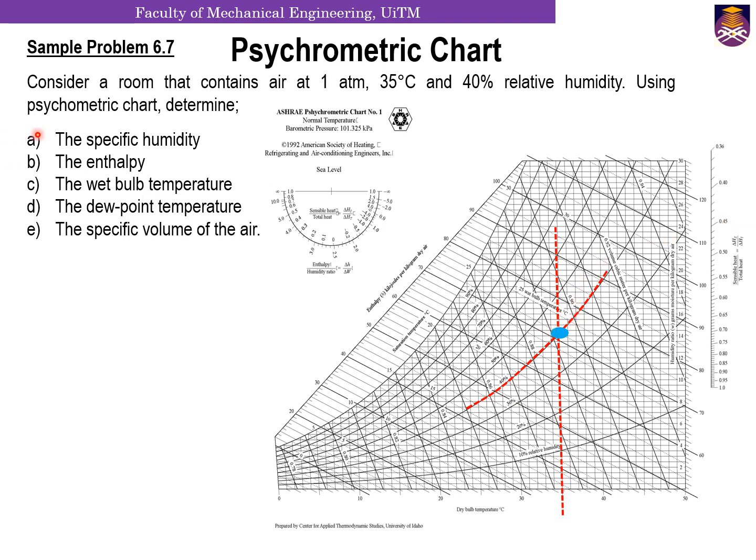Now based on this, we want to find what is our specific humidity. So to do that, from this intersection point, you pull a line straight horizontally so that you cut this axis, y-axis, to find the value of your specific humidity. So wherever you find the intersection here, so based on the scale given here, you find out what is the value. That will be the value of your specific humidity. Next, to find the enthalpy, we draw a line again parallel to these lines until we intersect this scale here, and then the value at this particular point based on the scale given to you,